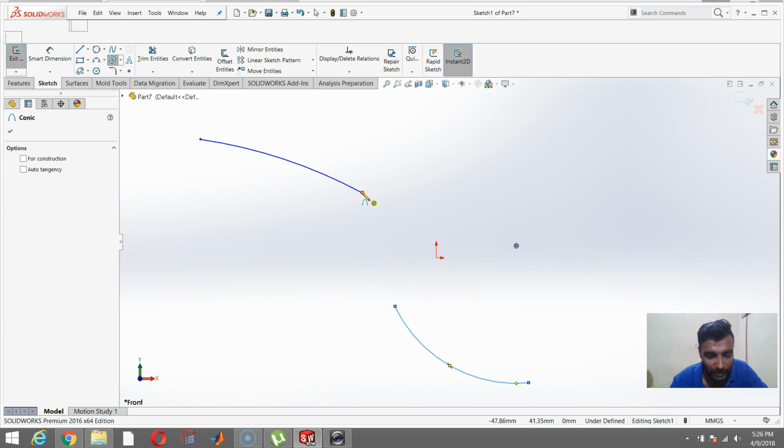So all that you need to do is to select the 2 edges, like 2 points, and then now if you can see here, you need to specify the 2 points. So there is point 1 here and then point 1 on the yellow line. These 2 points are different. The first point, which is close to my pencil, is actually the point where the tangents to both the curves actually meet, right? So I can just place it here, and then I need to specify my rho value.